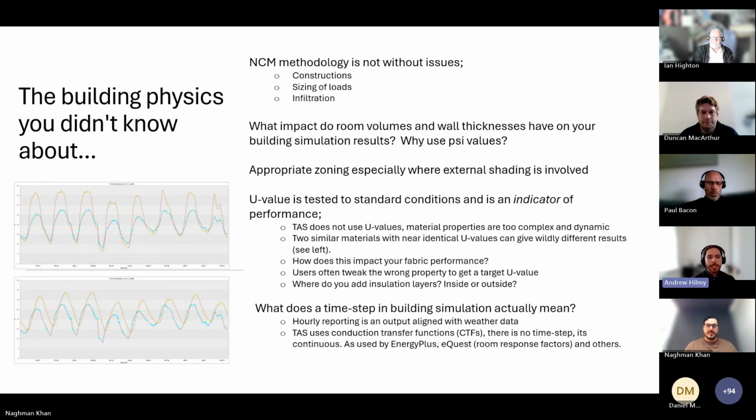With NCM, you don't zone vertically; you have to ensure that you have the same zone vertically. But if you're doing an overheating analysis or a proper analysis, you can use different zones vertically and see the stack effect. You can see that in the TSD file, and you get the right temperature gradient. It's going to be hotter at the top, I can guarantee you that. And that's something you can capture by zoning appropriately.